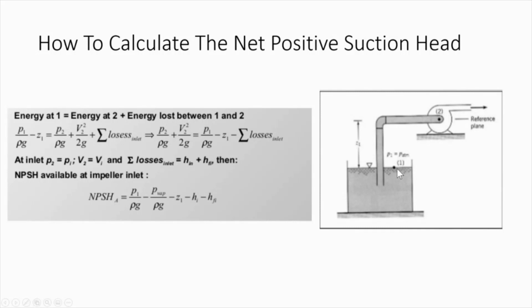What are the forms of energy at point A? You've got pressure from atmosphere. It can be a closed entity, so the pressure might go up as well. You have a height. You have a z. Whenever you are measuring these heights, let's say that's point 1 and 2, it's important that you always measure all the heights in a system from a single point of reference.